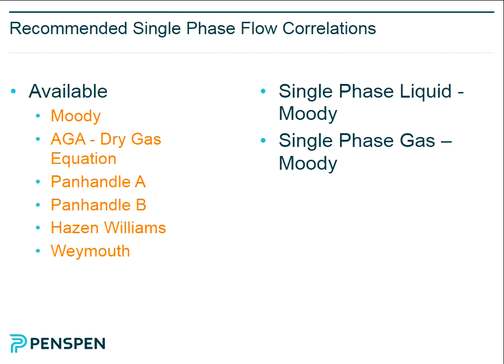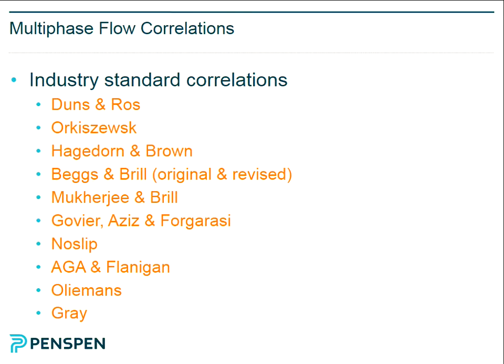So when you're doing a multi-phase flow analysis, you have a range of applicability for your particular set of circumstances, and you'll switch from one to the other. So when you go from your deviated well to your vertical well to your pipeline to your riser, you'll switch between the various flow correlations because of their various applicabilities. You should have this on your blackboard.